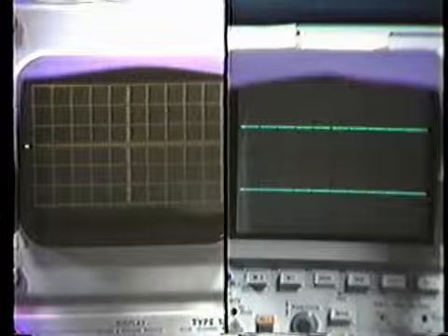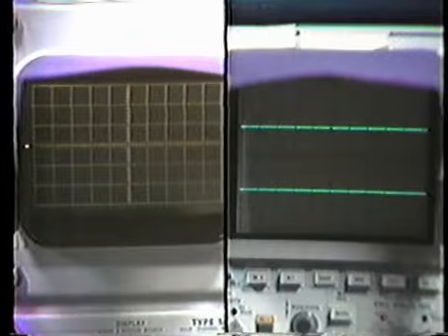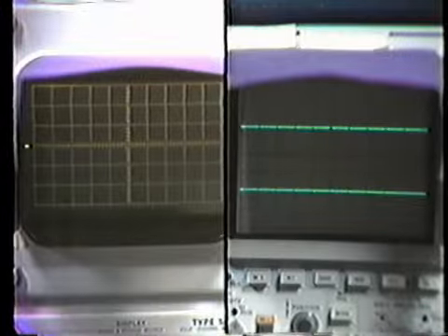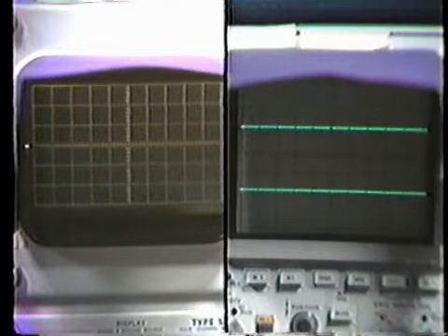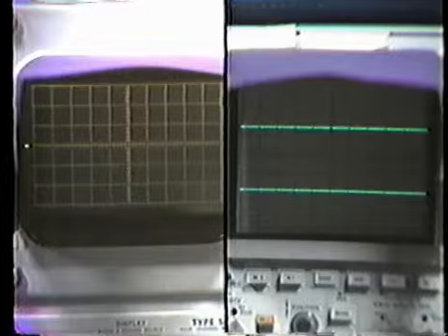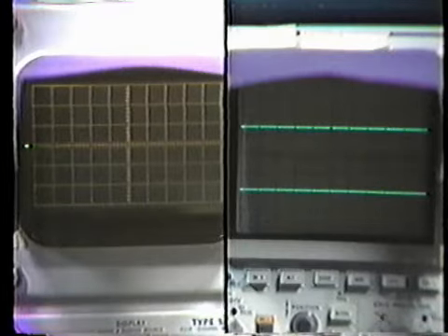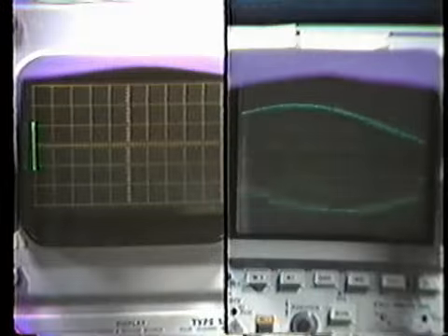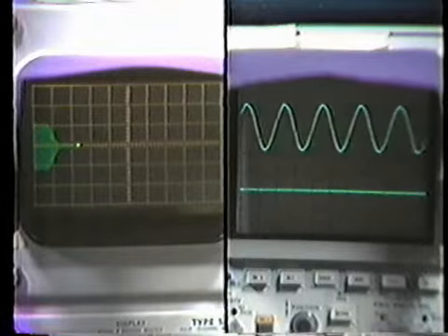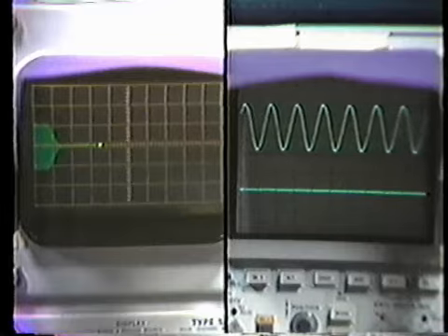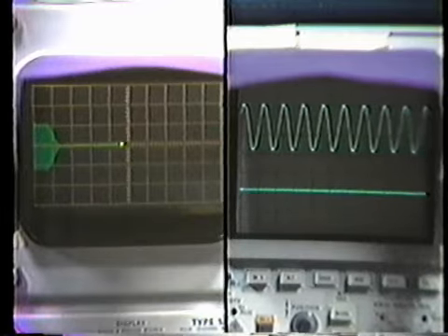And in addition to observing the frequency response, let's also listen to the output sinusoid and observe the attenuation in the output as we go from the filter pass band to the filter stop band. Again, a 20 kilohertz sampling rate and a sweep range from 0 to 10 kilohertz. Now, of course, we're in the filter stop band.